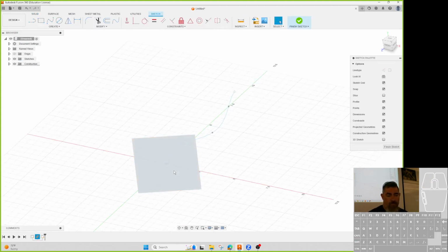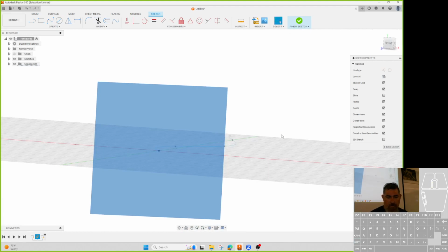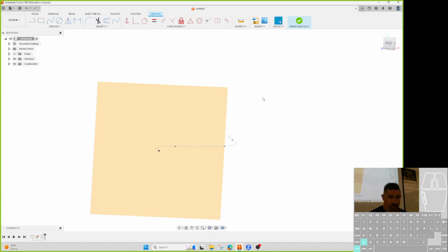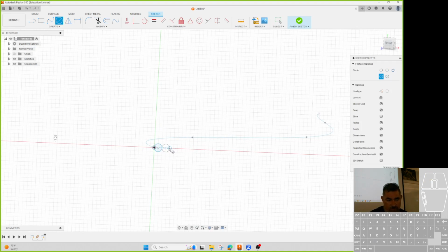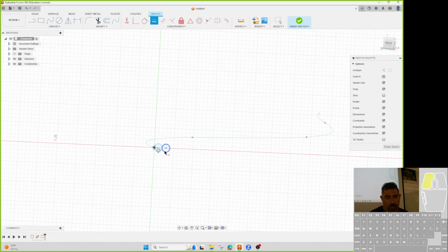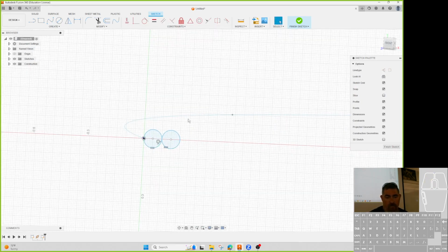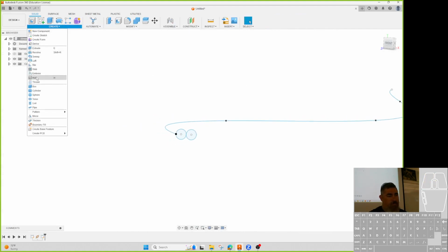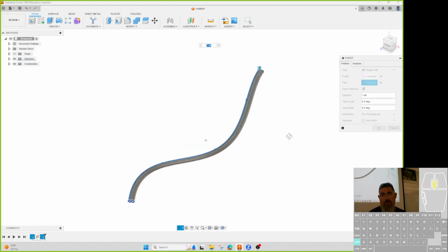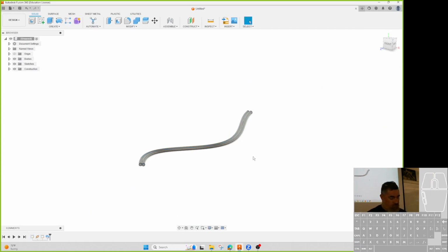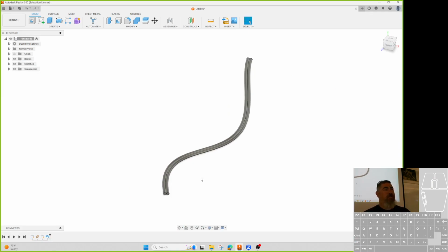So now I can go in here and create a sketch. Make things equal. And then now I can sweep those. And I get a nice double wire. Okay, does that make sense? So this is one I can't do just by offsetting because the curves have to change and everything. So this is one of the times I would draw the same thing a few times and not try and use a pattern, because there's no way I could pattern this.